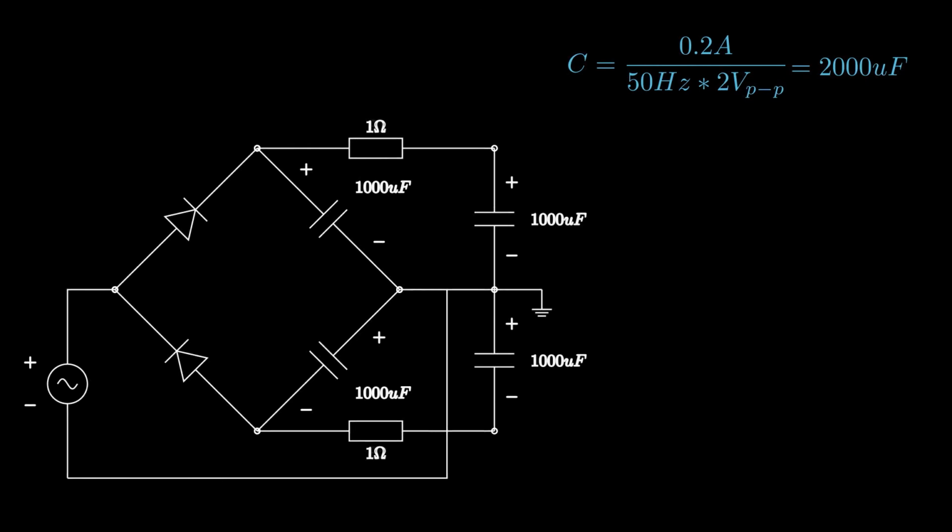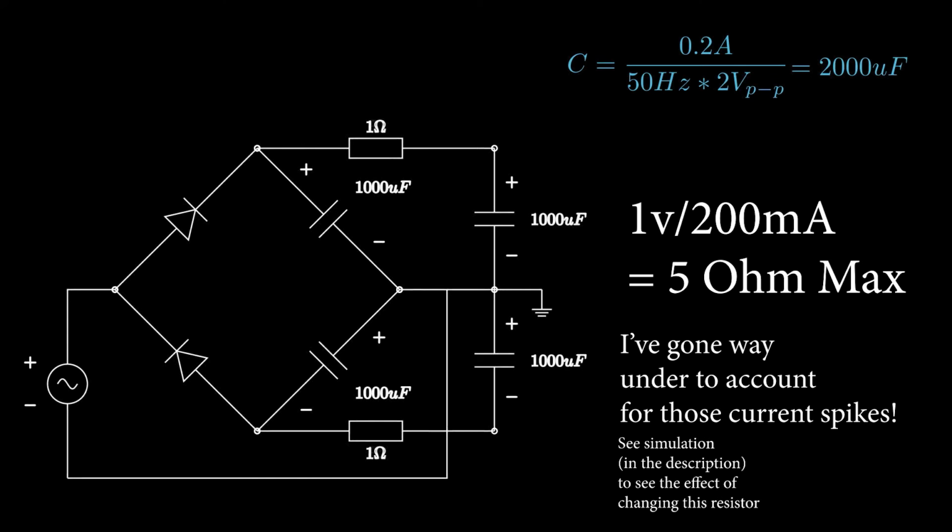Just be sure to use capacitors that are rated for the appropriate voltage across them. So you want to size this to drop no more than half a volt, say, across it. I've gone for 1 ohm here. And remember to use 1 watt or better resistors.